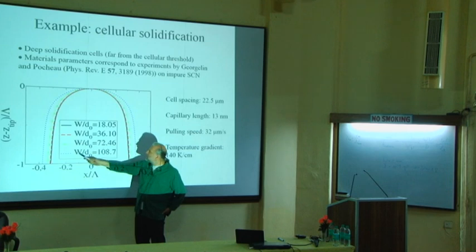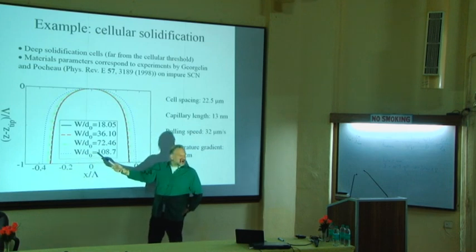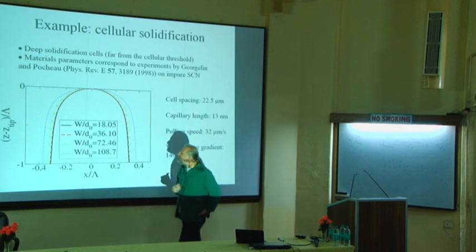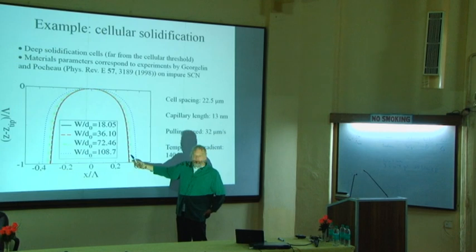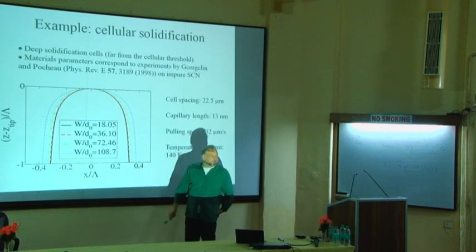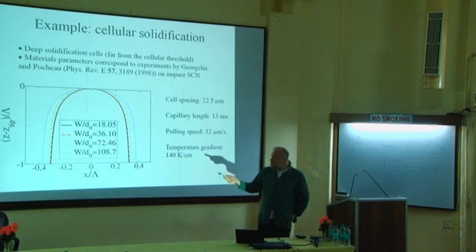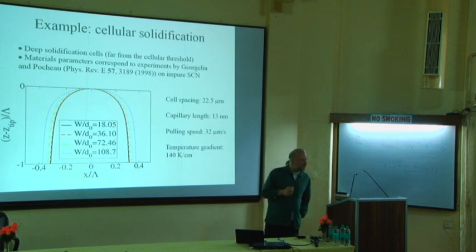And you see the blue dots are the thickest interface, and the black line is the thinnest. And you see that for the last two values, the interface shapes almost exactly superimpose, which means that, again, this model converges well. So you can get results that are independent of the interface thickness that you choose.